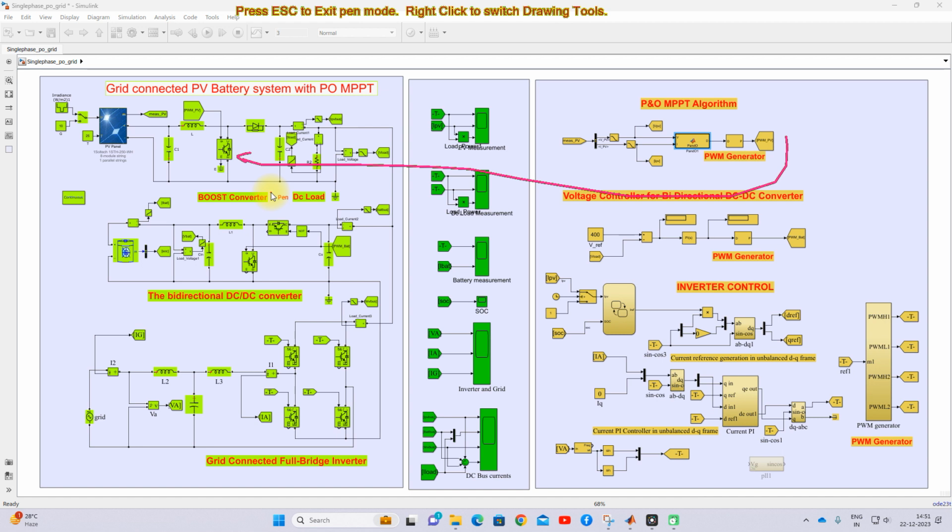So next, we are going to connect that PV system to the DC bus, as well as use a battery in the system. Why are we going to use a battery here? During night time we don't have any solar irradiation, so we need to use some stored power to supply the load during night time.